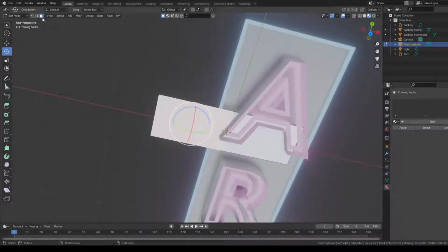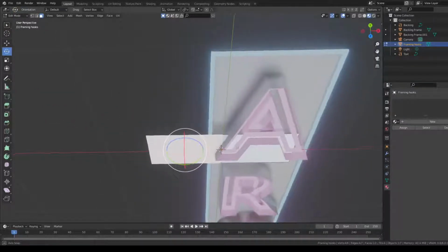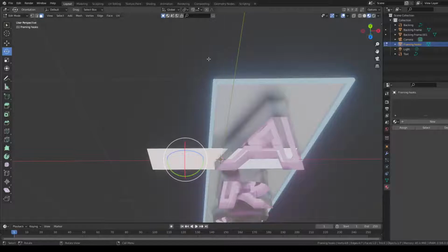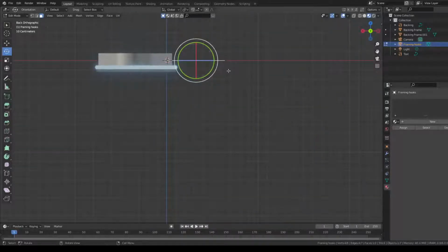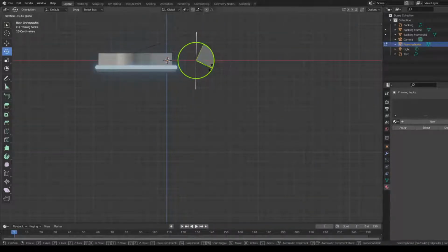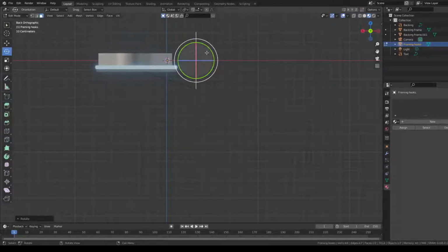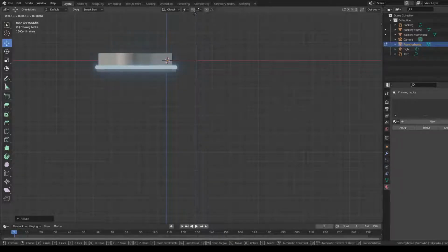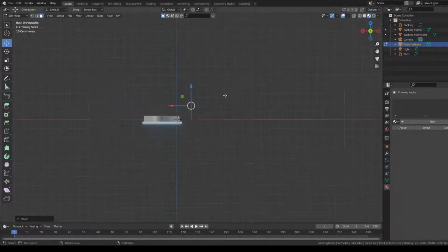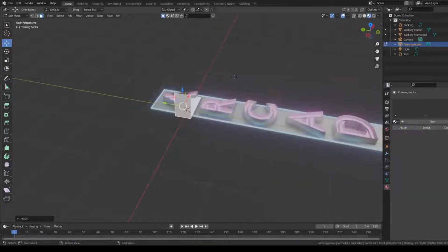And actually, okay, yeah, and then hit rotate, and if we go to Y, right, you can see this is the axis that'll give us a parallel motion, right? So what we want to do is hit 90, and you see it kind of warped it. We're going to just kind of scoot that back up until it touches the line, right? So we generally get a 90-degree angle, right? And this is going to be our hooks.